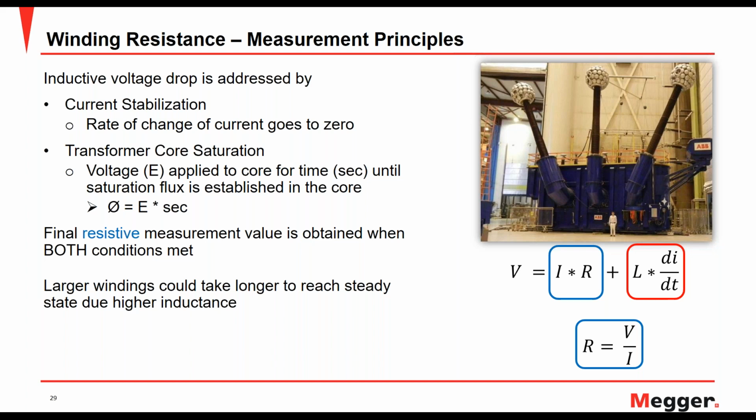Now, it's noteworthy to understand that if you have a large winding, for example a generator step up transformer or transformers of that sort that have a larger winding, it could take longer for the reading to stabilize because of the higher inductance of those types of windings.